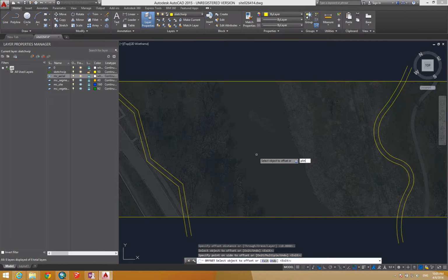So let's do a polyline again. And hit escape, P-L-I-N-E. You have to be careful. Sometimes you'll be stuck in a command and not even really realize it. And I'll start my polyline here, and this is going to represent the distance of my bridge. And keep in mind, this is very much still just sketching.